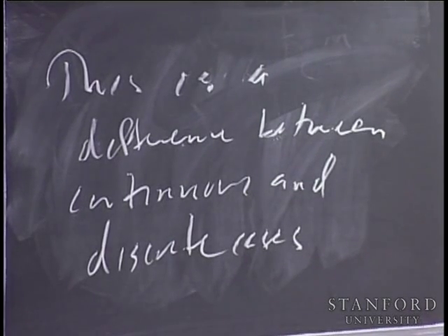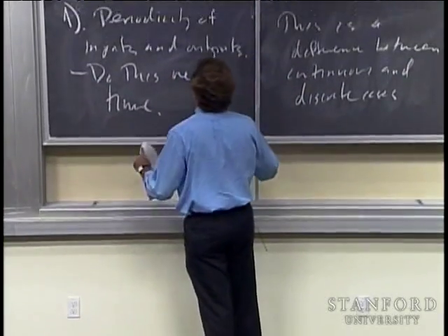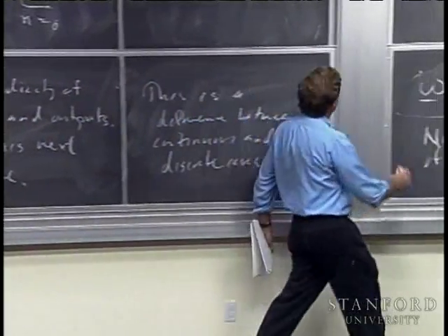But as it turns out, you are really compelled by the definition of the DFT to extend those signals to be periodic of period capital N. That is to say, to be defined on all the integers. So we'll leave that up there because it really depends on the formula.